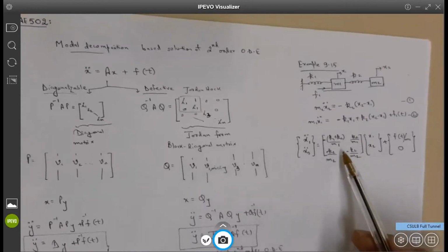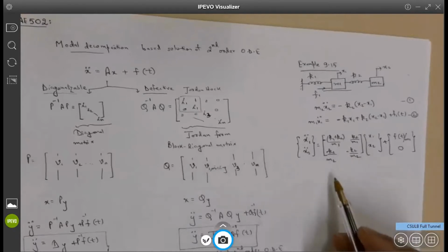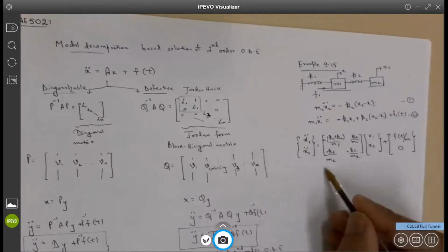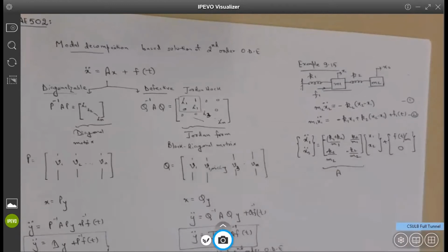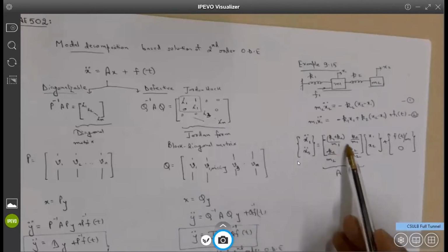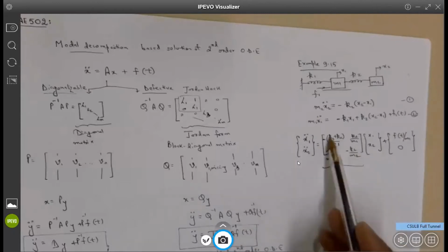Let me know if you are following. Is everybody good so far? Yeah, I follow. Great. Thank you. Is this a rewrite of the matrix? Because last time we used the mass matrix as a diagonal matrix. Will it yield the same result? Yeah, I already took the inverse. If you take the inverse of the mass matrix and multiply it with the stiffness matrix, you will end up with these terms.